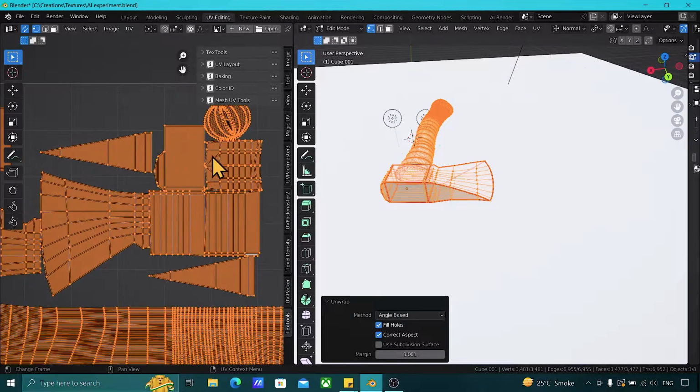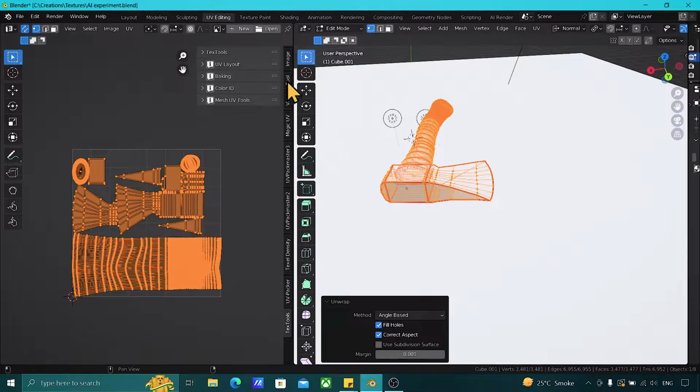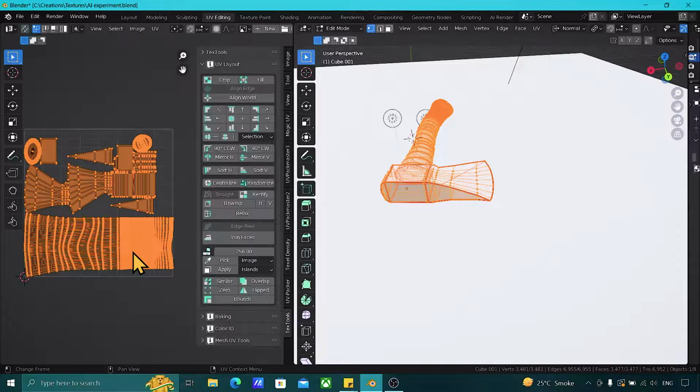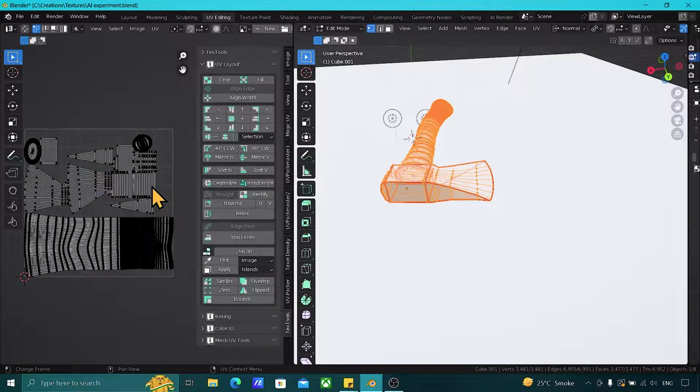All right. So this is the current UV, and now it's time to use the UV tools properly. So go to the layout, press A, and click on overlap. So make sure that there is no overlapping of textures in your UVs because it is very important, and it's problematic in software like Unreal Engine.